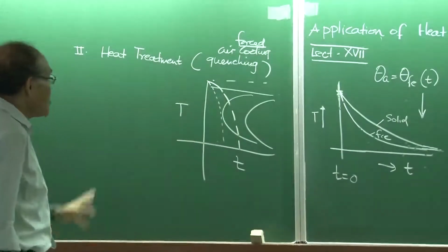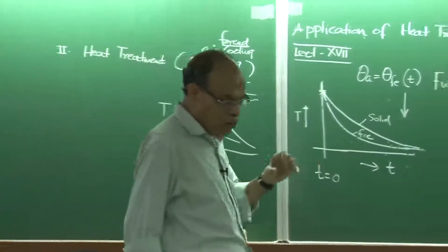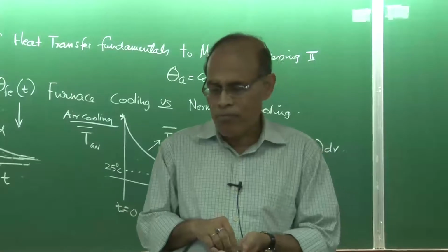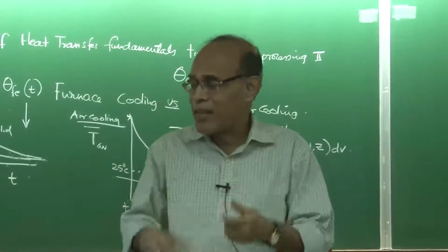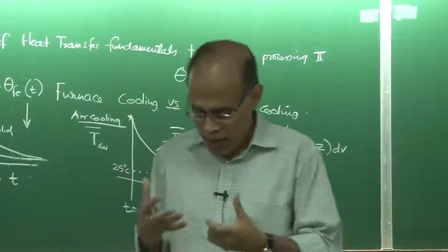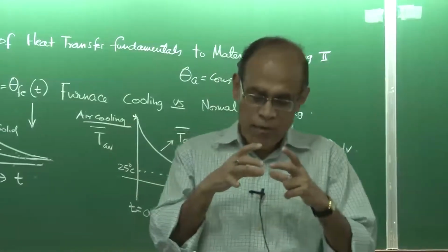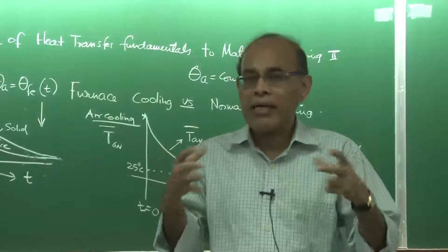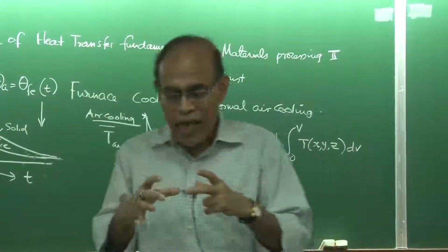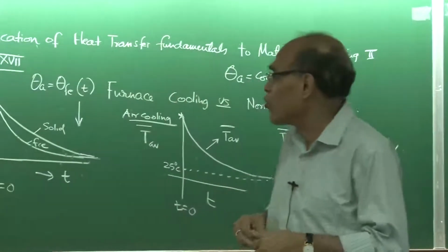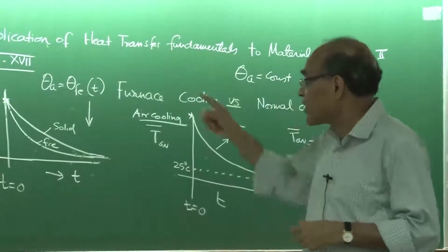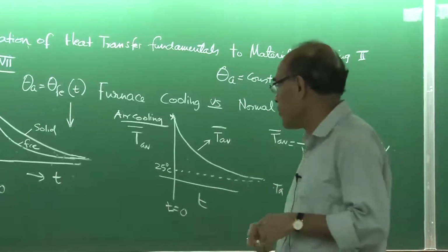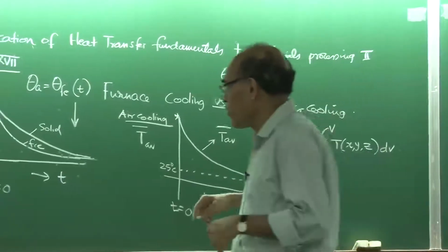But wire rod cooling is used to improve the properties, because the grain size is related to the material property and performance. Finer grain size gives us, in layman's terms, better toughness or better strength, and coarser grain size gives us, as you all know, relatively poorer strength. And the grain size is going to be dependent on the rate of cooling, for example.